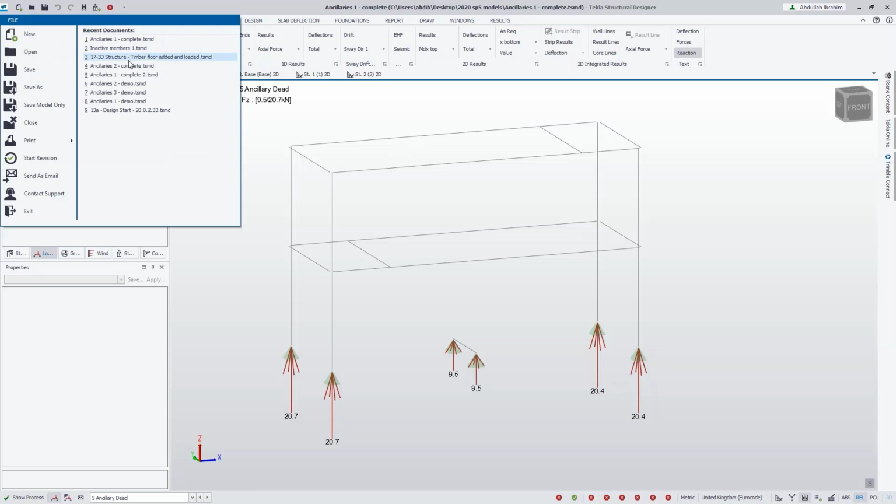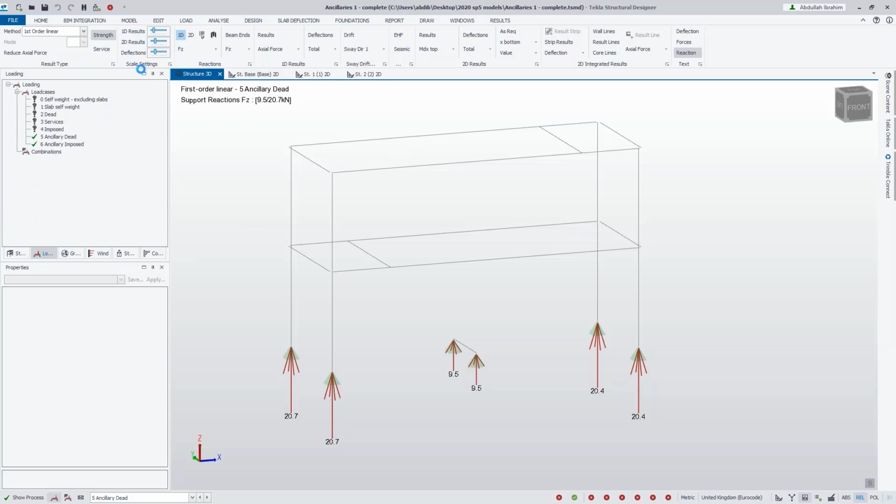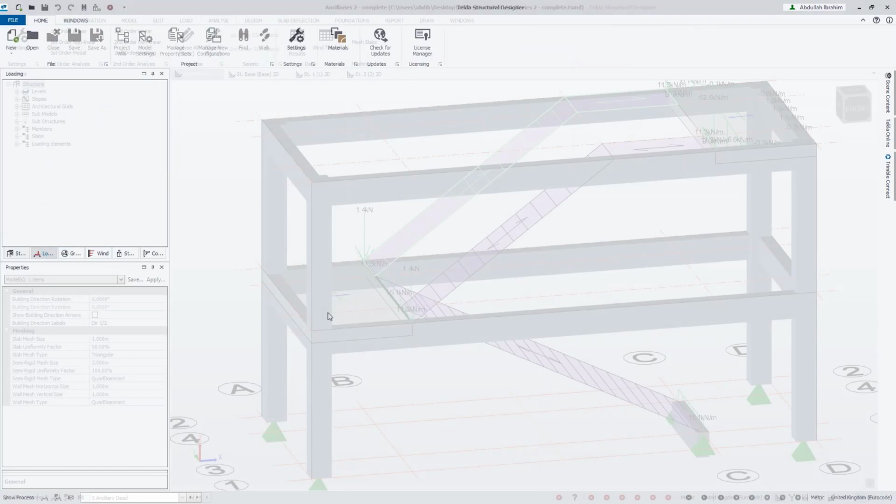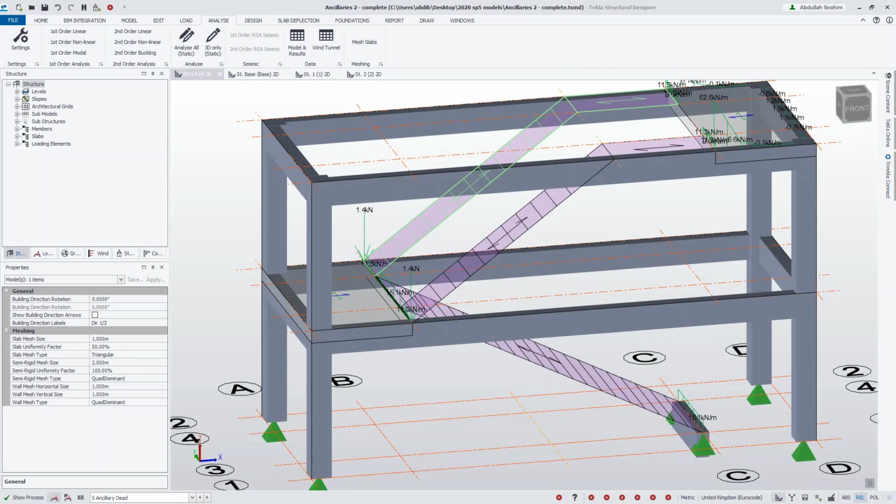I'm now just going to look at another model this time. So this is the same model that we had before. So looking back at this flat slab example where we'd modelled a dummy analysis element, the dummy analysis element is there to simply decompose the loads because of the limitation with regards to having two flat slabs.